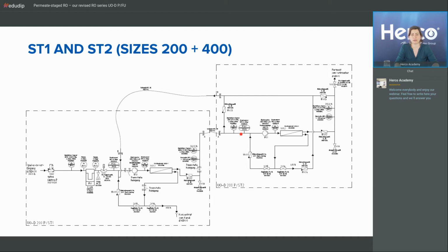You have the pressure sensor, you have the high pressure pump, and your membrane. And then you go down with a concentrate. Now you come out with a concentrate, you have number 1, a concentrate recirculation. That is sometimes necessary to achieve a sufficient overflow rate to prevent scaling. Then you have actually a concentrate outlet, that's this one. And the concentrate, remember, goes back to the first stage. So the concentrate is connected via hose, that's the BB connection, and goes back.